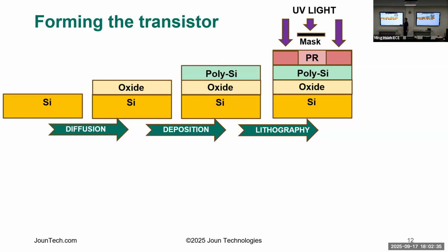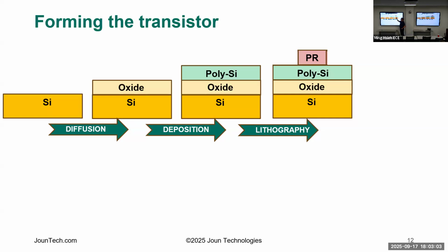And the masks are used such that there's a special material called photoresist. And when the light hits it here and here, that photoresist will stay soft. And underneath the mask, it stays hard. So when you come in and later do a chemical clean process, the two places where it was soft got washed away, this stayed on there. And so what you've just done is you've done the stencil. The mask had a layer here and it went down onto the photoresist.